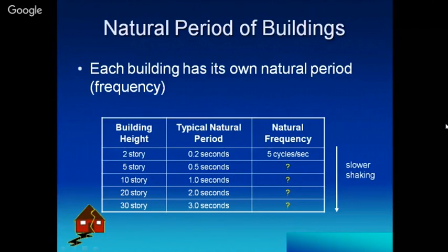2-story, 5-story, 10-story. All these things, whatever is being depicted in this table, are being calculated empirically using formulas, and it is giving the typical natural period of that particular building, depending upon how many floors they are. And depending upon that time period, the frequency is being calculated. T is equal to 1 upon F. So we can use this just as a general idea of how many stories a building could have, what natural time period and what frequency it is going to finally give us, and we can have a general, initial view of things.